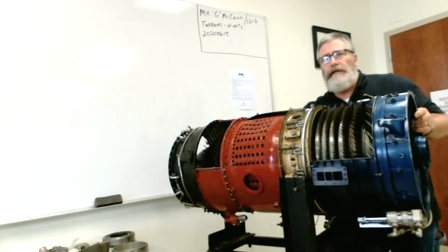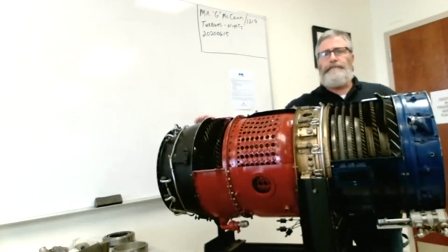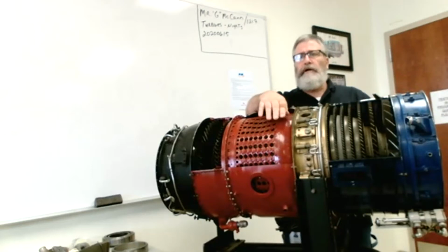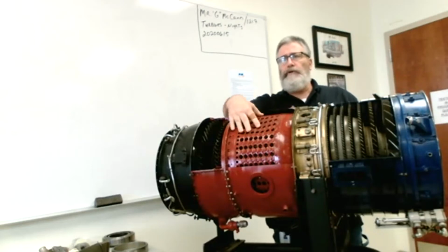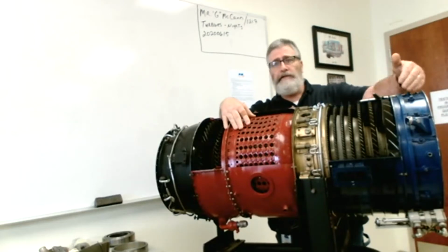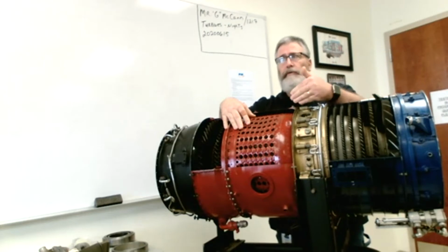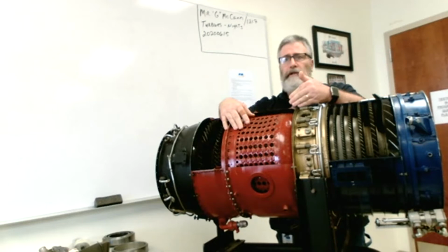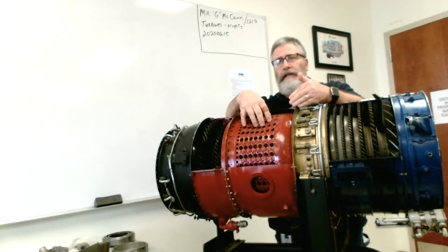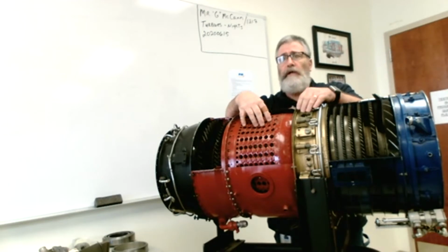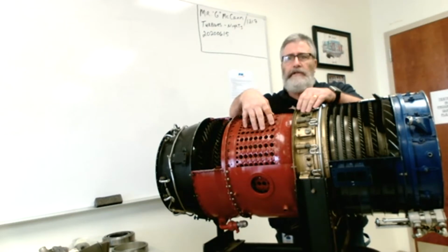So we move past the diffuser, which is a divergent duct, and now we slow the air down before we introduce it. Now, an interesting fact is the air is pumping in here, but out of the 100% air that is coming into this engine, only about, just using general numbers, 15 to 25% actually goes into this combustion chamber liner and supports combustion.